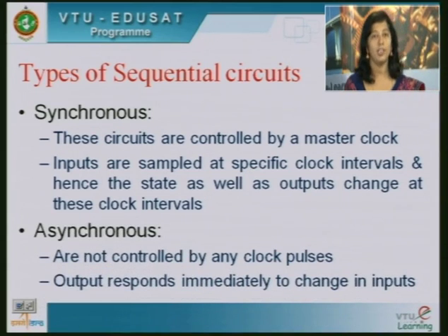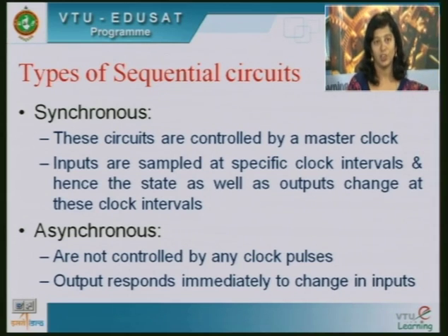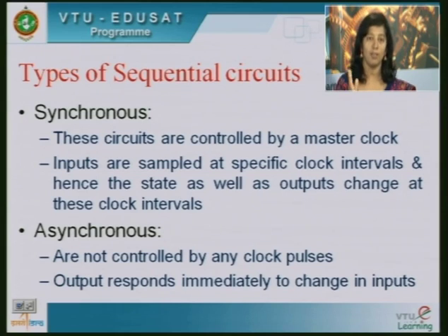The other type of sequential logic circuits are asynchronous sequential logic circuits. In asynchronous sequential logic circuits, we do not have any master clock or clock pulses, and many times no enable signal either. So, the output responds immediately to changes in the input values. Whenever the input changes, the output is going to change. This kind of circuit is called an asynchronous circuit. There is no synchronism or matching with one particular edge of the clock.